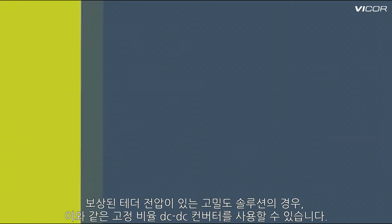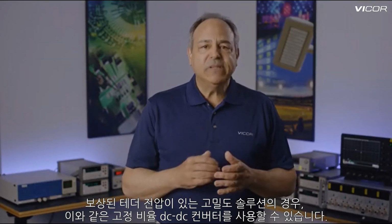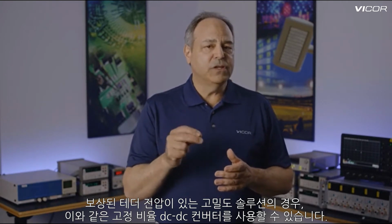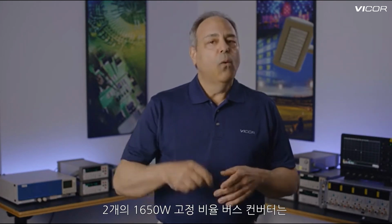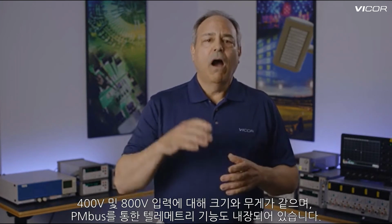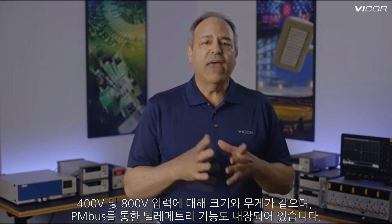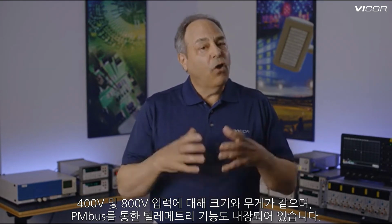For a high-density solution with a compensated tether voltage, you can use these fixed ratio DC to DC converters. BCMs are less than half the size and half the losses compared to regulated converters. Two 1,650 watt fixed ratio bus converters are the same size and weight for either 400 volt and 800 volt inputs, and also have built-in telemetry using PMBus.